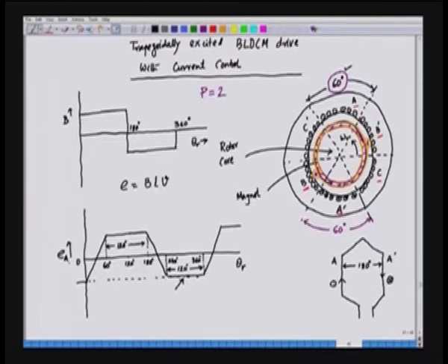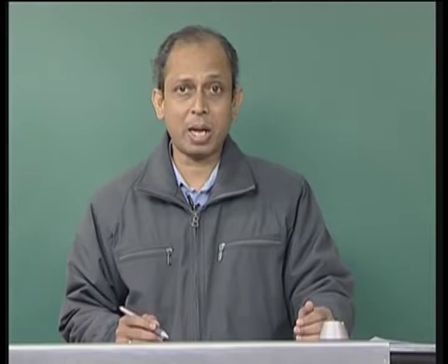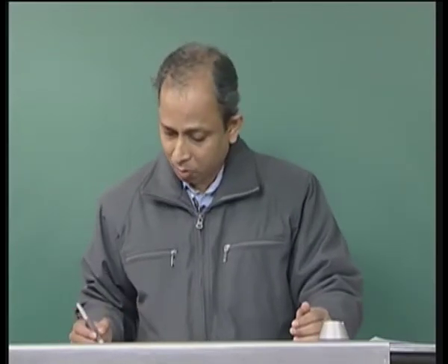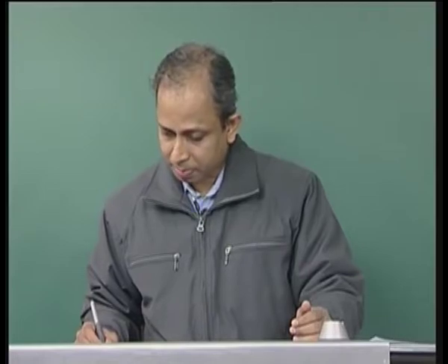So, if it is an induced EMF in phase A, phase B, phase C are symmetrical. So, whatever is happening to phase A, the same thing will be happening to phase B and phase C respectively, but after a delay of 120 degree. It means phase B induced EMF will be shifted from phase A by 120. So, we can plot the complete induced EMF in the following fashion.